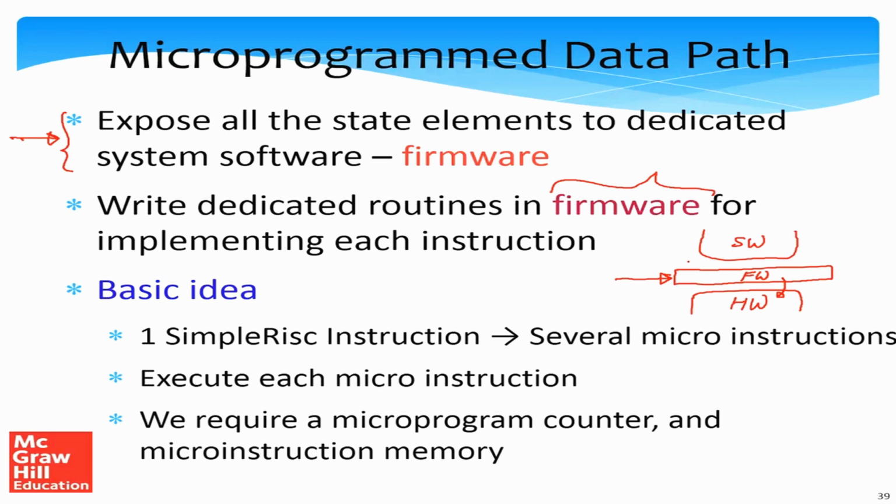So let me talk about the basic idea of microprogramming. In this case, we take one simple RISC instruction, like add, subtract, multiply, and we break it into several small microinstructions. We execute each microinstruction pretty much one every cycle. So for an add instruction, we replace it with a microprogram which can have many microinstructions.